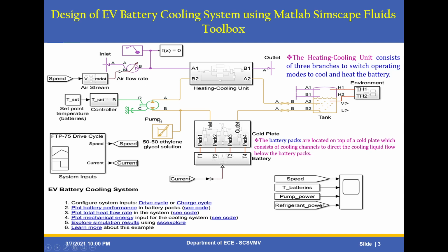Based on that, by using this model, you can configure the system inputs, drive cycles or charge cycles. Also, you can plot the battery performance in the battery packs, the total heat flow rate in the system, and the mechanical energy input for the cooling systems. These are done by using the interactive Simscape Results Explorer app available in Simscape Fluids. You can easily see the simulation result in SSC Explorer.